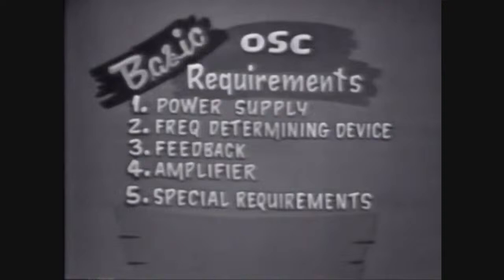There may be other requirements depending on the application of the oscillator, which you'll discover when you study a particular piece of equipment. But the main idea is that all oscillators are basically the same. So whatever the type or the name of the circuit, all oscillators will require a power supply, a frequency determining device, and feedback, usually from an amplifier. Now, if you apply these basic principles, oscillators will be much easier to understand.